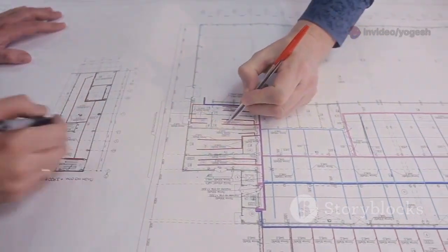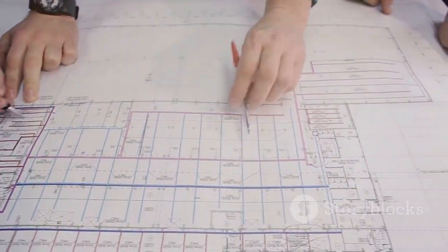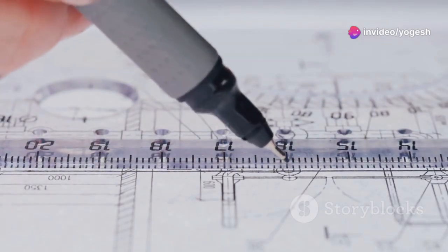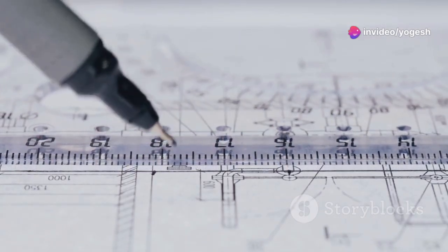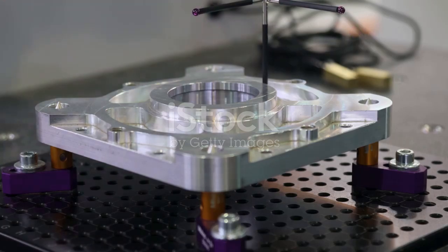Specify each target's location with basic, boxed dimensions. These are theoretically exact, with no tolerance. Consistent naming and clear placement ensure anyone can interpret your intent. This method locks down the part's orientation and origin for all subsequent measurements.